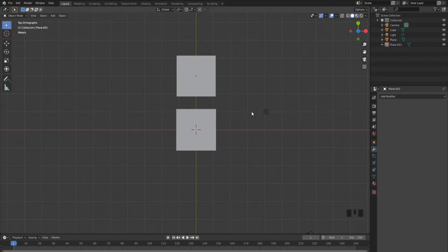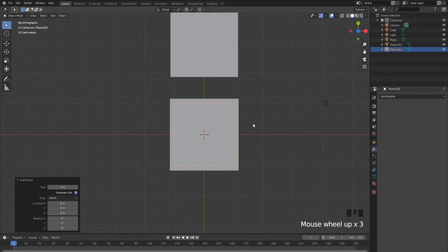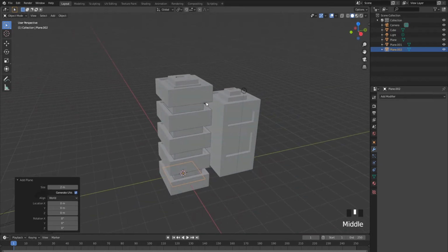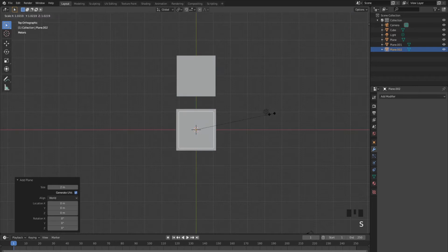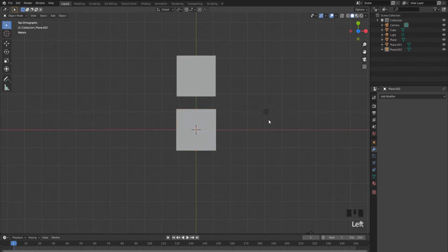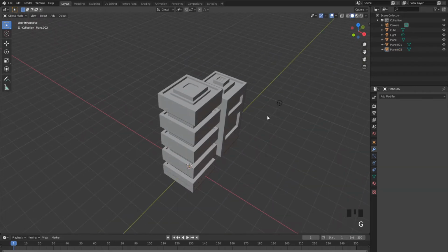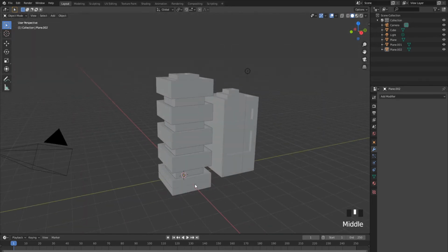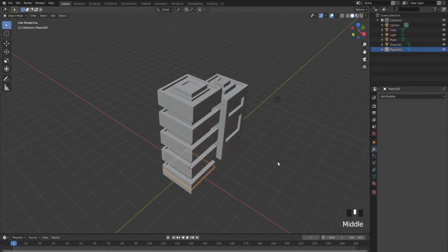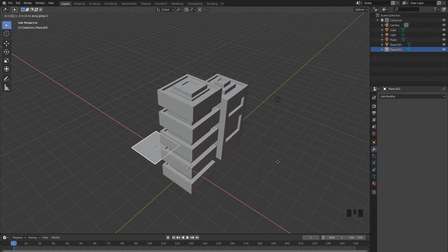So now I'm going to go back to top view, shift A, add another mesh, and expand this a little bit too, just so it's around about the same size. We're not being exact with this one. GX. Oh, well, if I was selecting my face first, GX, and it was 3. But remember, we're going backwards here, so this is -3.